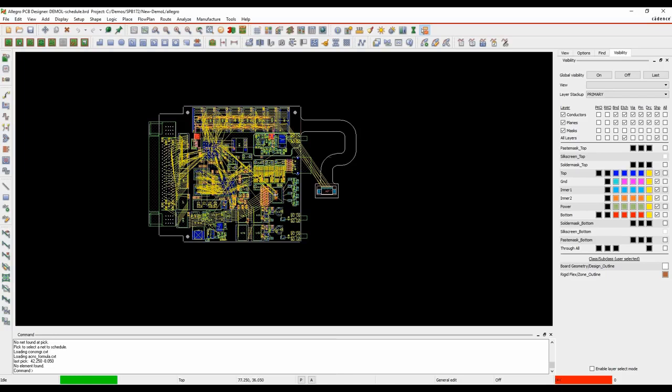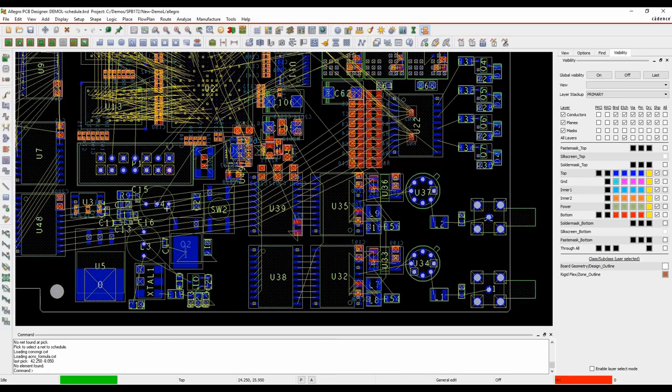In OrCAD Professional, if I was going to schedule a net, effectively that writes a user-defined schedule into the wiring worksheet, but you have to do that for each individual net in an OrCAD Professional-based license. With Allegro, you have the ability to actually do it once and then create an EC set from that. So we'll go through that now. We'll start off with a net here.